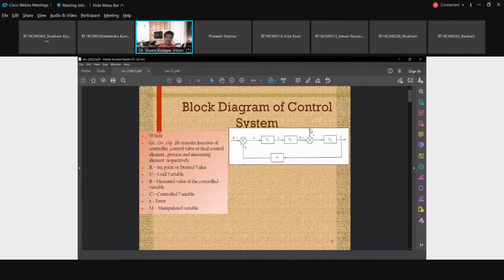As you know, the blocks in block diagrams represent transfer functions, and the arrows are nothing but the means of flow of information. It may be pneumatic, we will discuss that. But the nomenclature we place over here is nothing but the Laplace transform of the deviation variable of that particular variable. Okay. P, GC, GV, GP we are using.